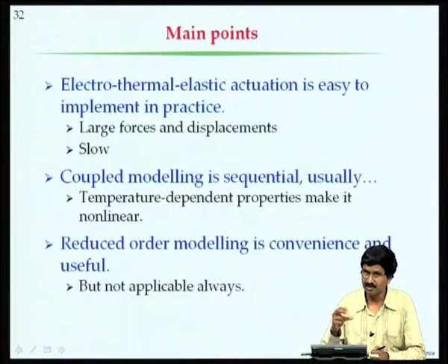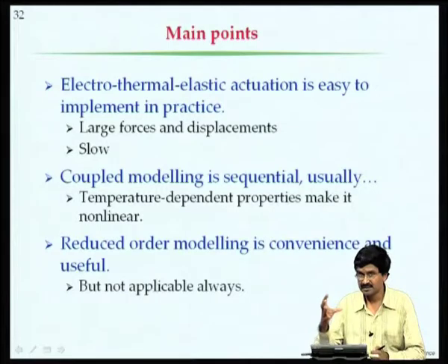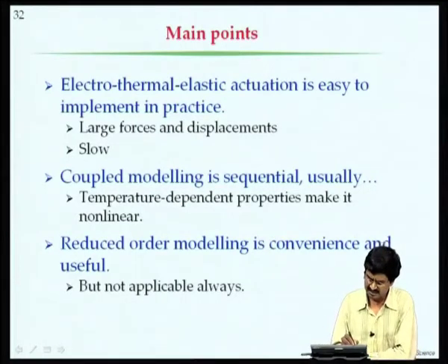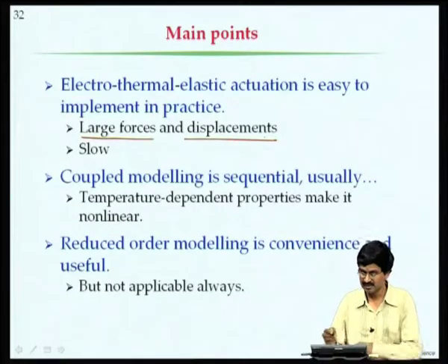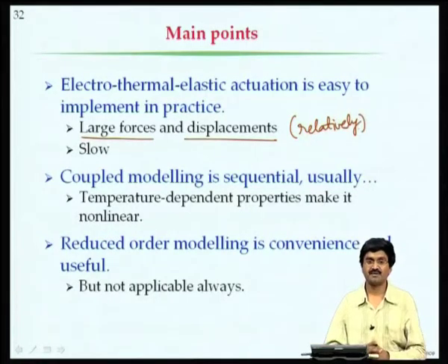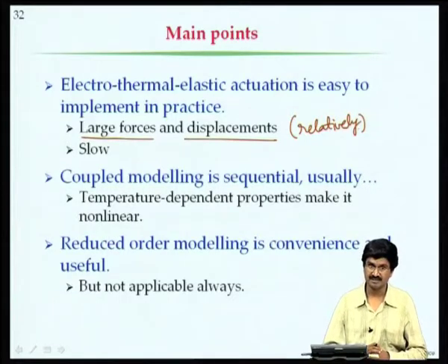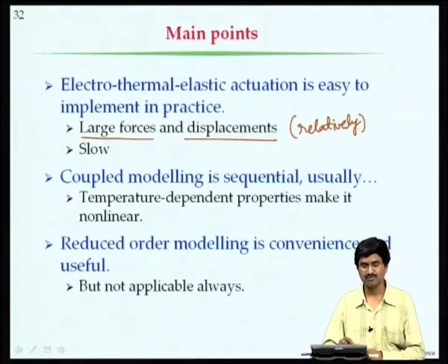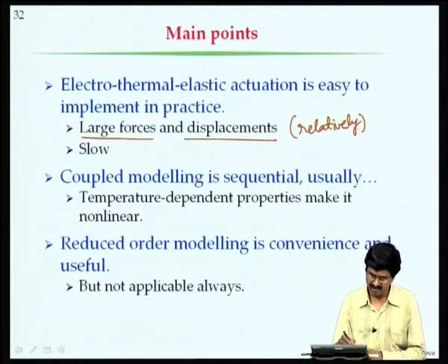So, if you have a gripper, there is no actuator pushing or pulling the gripper, rather the structure itself works both as an actuator as well as a mechanism, and can create reasonably large displacements and forces as compared with this only relatively, because we are not saying that we will get a large force like in electromagnetic or internal combustion engine type of actuation, but for micro scale reasonably large forces and large displacements, but it will be slow.